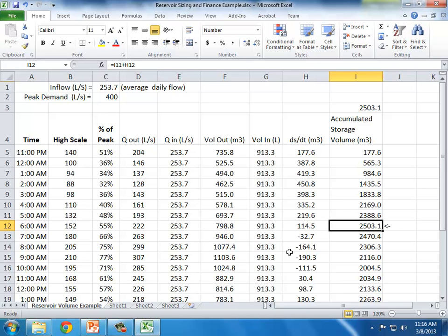If you got something instead of our rain, it's going to be variable input. Okay, yeah. So a stormwater runoff could be variable input, and that's absolutely true. Usually in a storm, there will be a peak, and then it'll taper off where it'll slowly drain the watershed for a while. And maybe if you are discharging to a river that you don't want to suddenly have its water levels rise, maybe you'd prefer that the outflow is constant. And so one situation where you'll have a case like this is a stormwater pond. And the analysis and design procedure is the same.